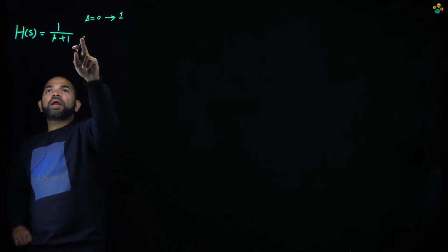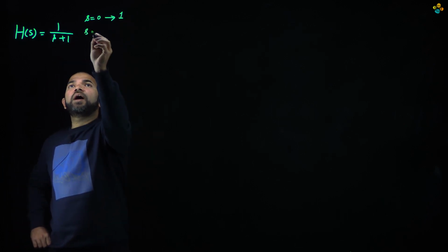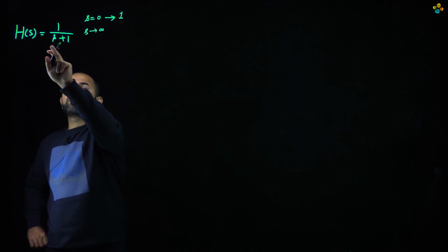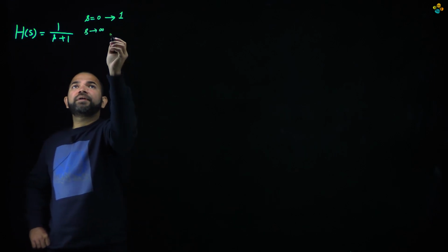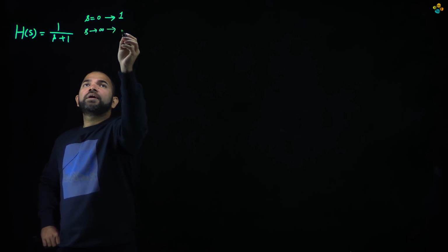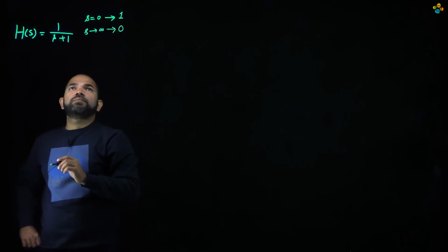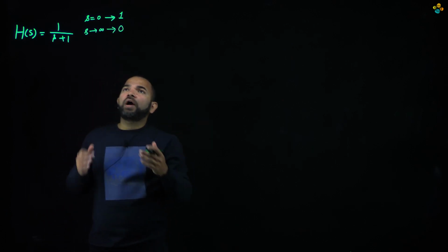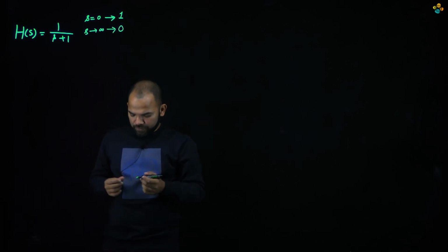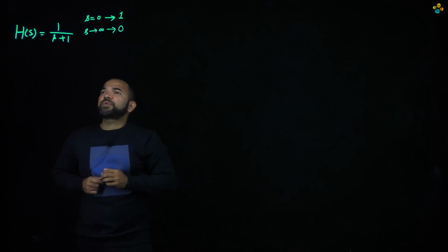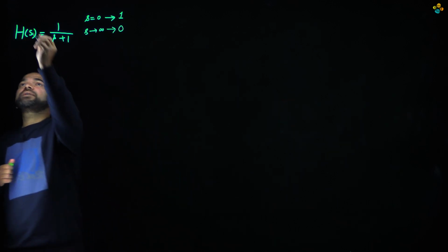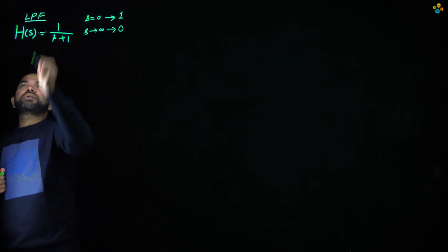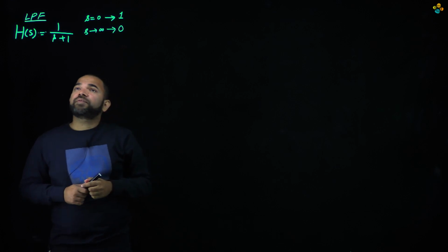When S is approaching infinity, this whole term is going to be infinity, and 1 by infinity is 0. So the transfer function reaches a value 0. So for lower frequencies, its transfer function is 1. For higher frequencies, the transfer function is 0. So this transfer function is basically a low pass filter transfer function.